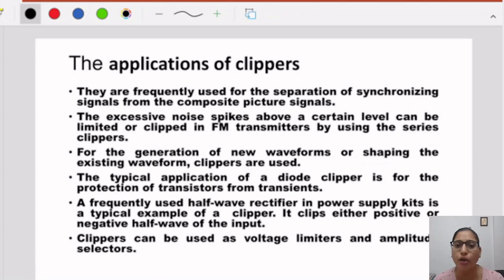We have one audio signal, one video signal and the color coding signal also. So this is the mix up. When there is a mix up of signals, these are composite signals. Now, when we use the output as a composite signal, there are a few signals which just synchronize with the system and which we don't need for the final output. So with the use of a clipper, we can clip them off.